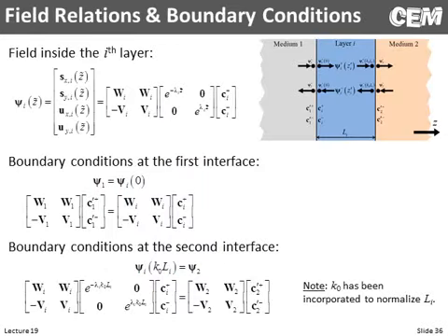So we'll go back, we will use the exact same type of scattering matrices that we did for transfer matrix method, and you should recognize the math. In fact, I've just copy and pasted this slide without any changes to it. So we have the overall field solution in some intermediate layer, and medium 1 and medium 2 right now are not layers. We have sandwiched a layer between 2 semi-infinite media, so they go off to infinity. And we'll calculate a scattering matrix associated with this. Now eventually we will turn medium 1 and medium 2 into just air, but we need to derive these equations because we also have our reflection and transmission connection scattering matrices to calculate.